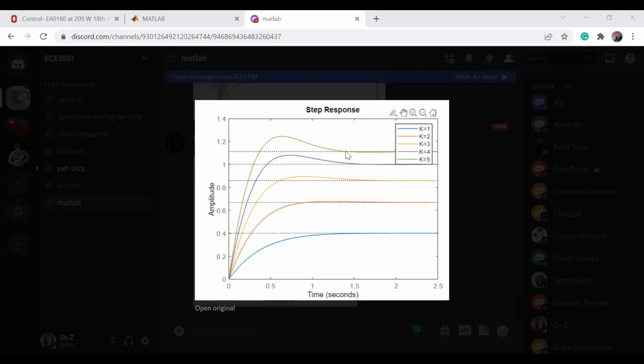Now, you could use theory, the equation, to find the controller parameters, or if you were here and you said, okay, let's say k was 1. What does it mean? There was no controller, right? If k is 1, the block would be 1, it becomes the signal. So there was no controller. It was still a feedback, but there was no controller design. In that case, k is 1, right? So the blue system is your system without a controller. Your job is to find a k that fixes the system.